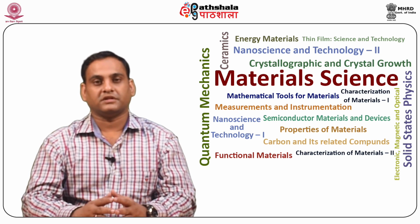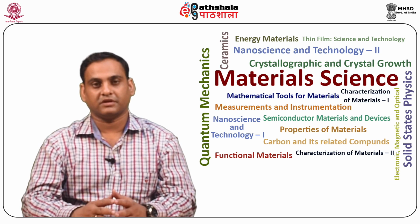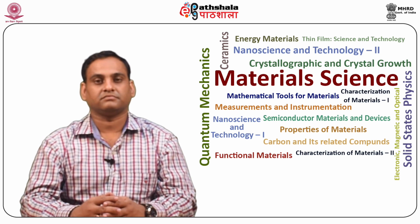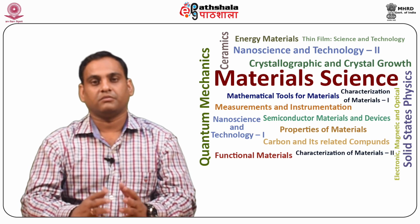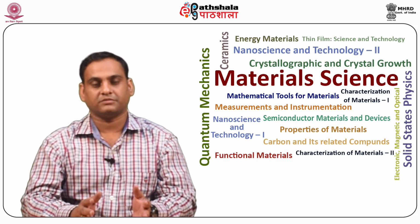These nanocrystalline materials find wide applications primarily for high-performance magnetic parts such as in electronic devices, common mode choke coils, power electronics, bead cores, noise absorbers, magnetic switch cores, transformers, current sensors, and electromagnetic shielding. Apart from the soft magnetic applications, these materials are used as magnetic refrigerants based on the principle of magnetocaloric effect and are also used in magnetic impedance purposes.